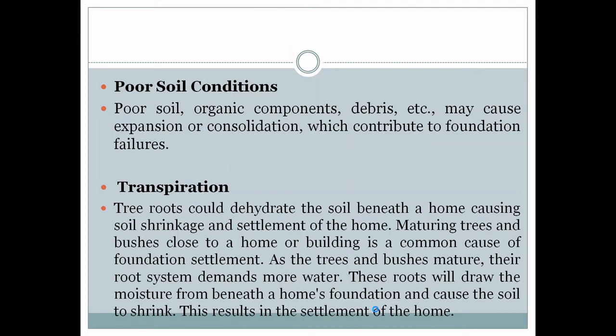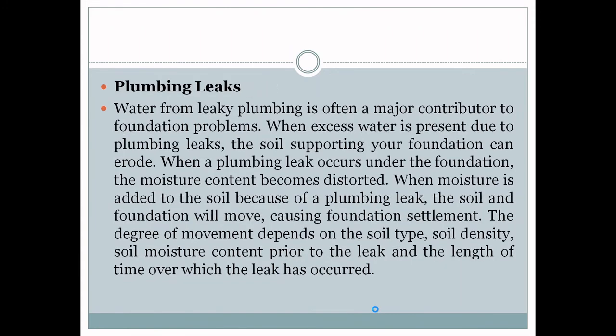So how can we prevent this? Provide a safe distance between the trees and the foundation to avoid damage due to the trees, or the foundation of the structure should be taken to a depth of at least 90 centimeters to minimize the cracking action.